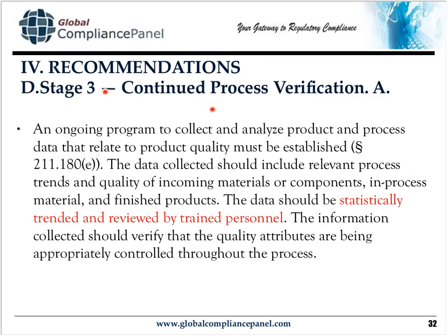Now, stage 3, continued process verification. This is where what we're looking at here is statistical process control. What you're doing here is you've basically validated your process at stage 2. And what you're doing at stage 3 is providing data and evidence that says that your process remains in a state of control. And to do this, you're looking at SPC, statistical process control.